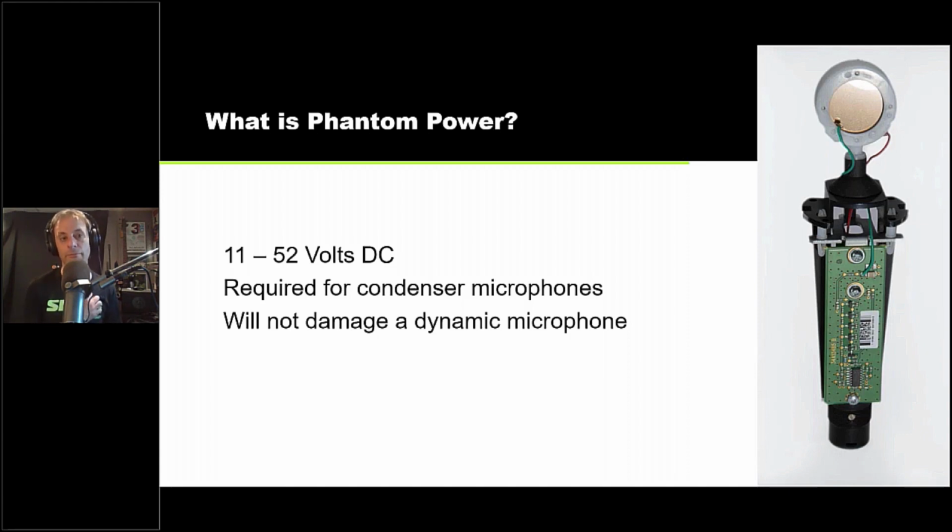You can turn it on or off, but that's a very common phone call that we get here in the applications engineering team at Shure. Someone had an SM58 dynamic mic, it was working great, but they decided they wanted to upgrade to a nice condenser gooseneck mic for their podium. They plug it in, they don't hear anything. Why is this mic not working? Typically, it's just because phantom power hasn't been turned on at the mixer.